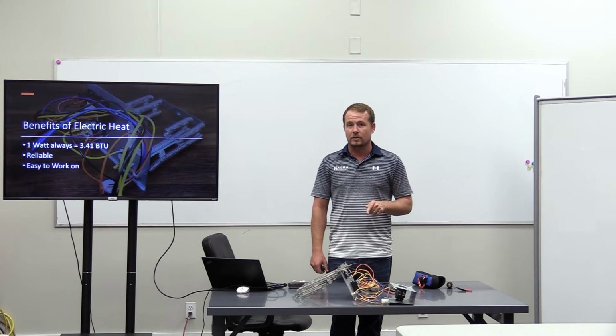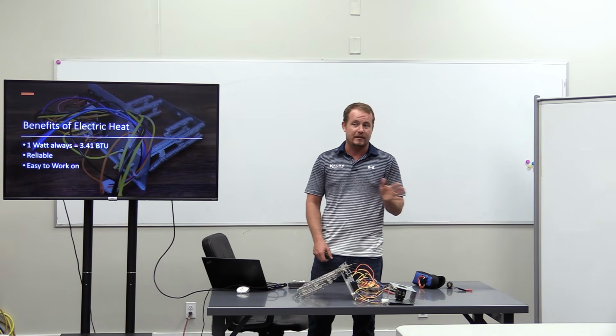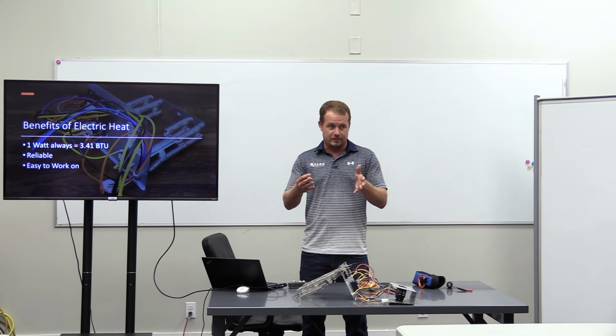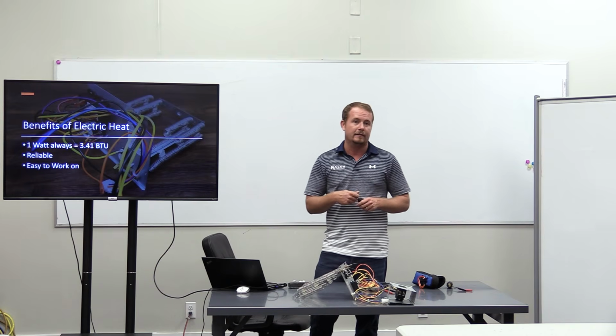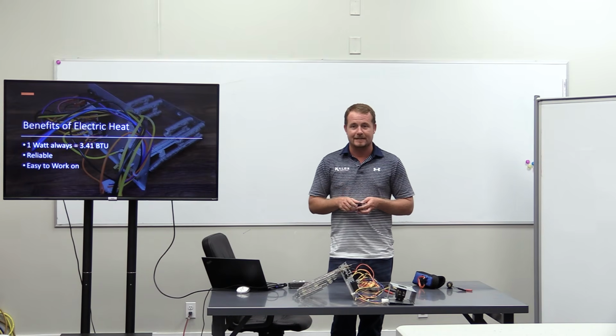If you think it's been a really long time, like in a commercial application where maybe the heat strips have never run, it's a good idea to just pull them out and clean them with some compressed air or nitrogen or something like that, rather than burning them off. So that's the lesson there.